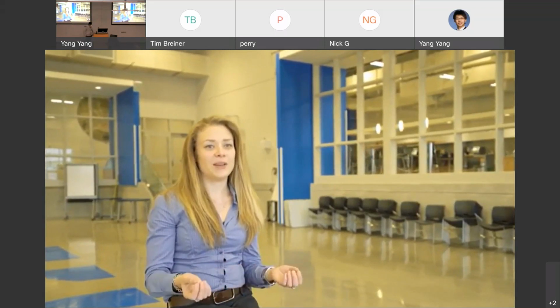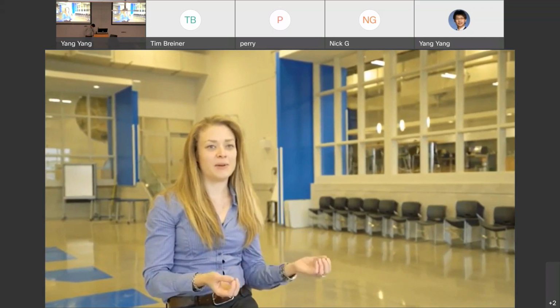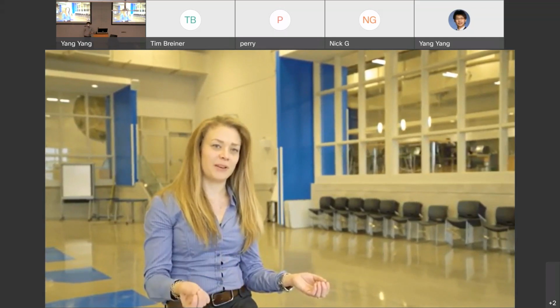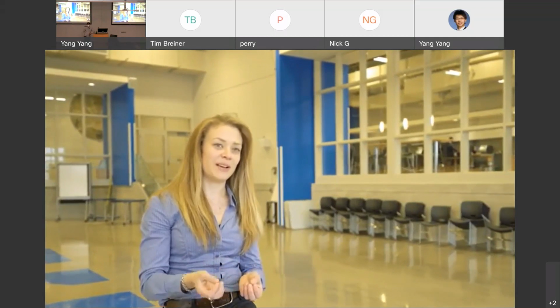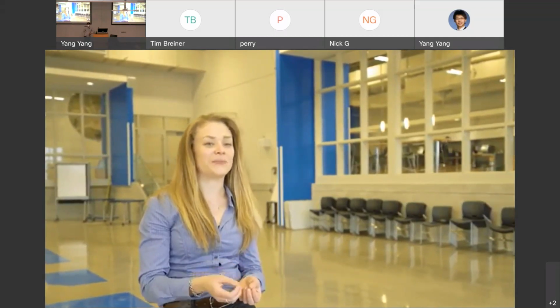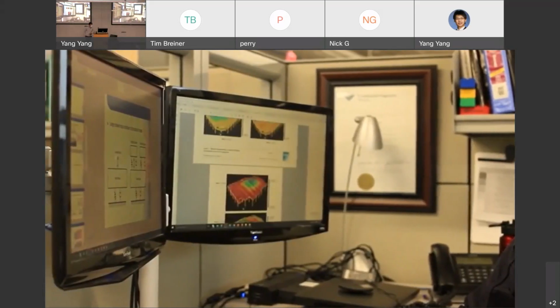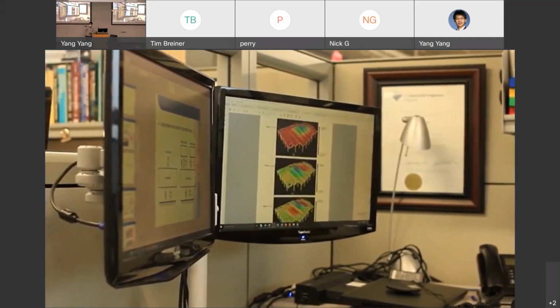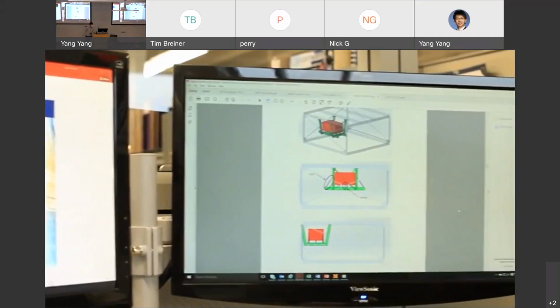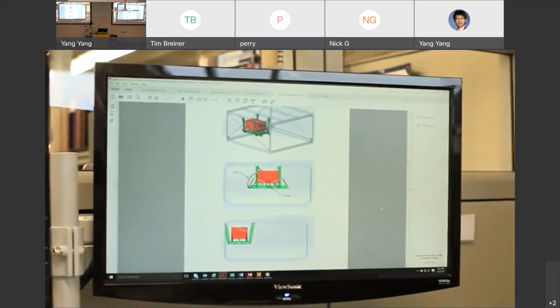We then used dynamic principles to combine the dynamic properties of the floor and the dynamic properties of the crowd to create a crowd structure model to which the dynamic loads of the crowd were applied. Our analysis showed that under certain loading scenarios, excessive floor motions were likely. To mitigate this response, we recommended tuned mass dampers, or TMDs.